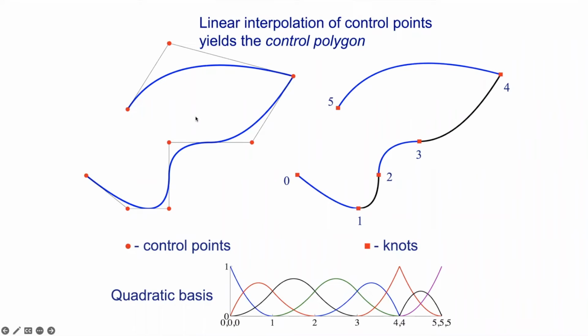Now, there is a dual point of view here, and it's really the finite element point of view. You can deconstruct this into so-called Bezier elements, which are like the typical elements of finite element analysis on the right. So you have 5 elements. Those are the images of the domains of the patch, the element domains. Say 0 to 1 is here, 1 to 2 is here. So those are the elements. But notice in this decomposition, that's exactly the same geometry. Okay, so your element mesh is living on your exact geometry.